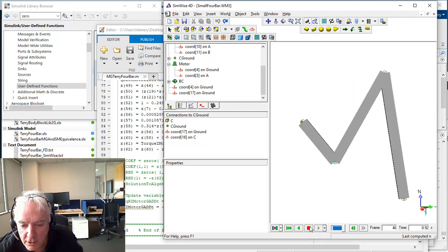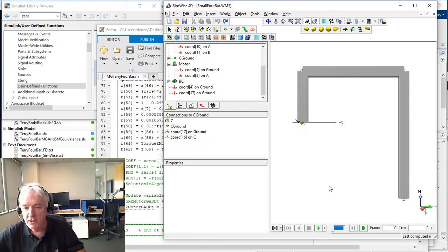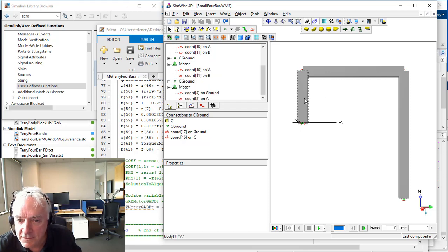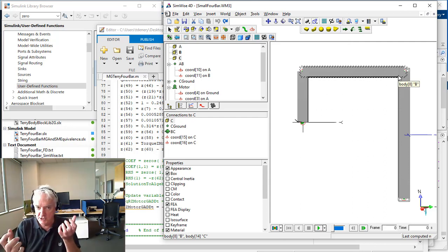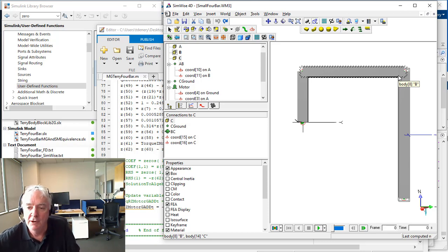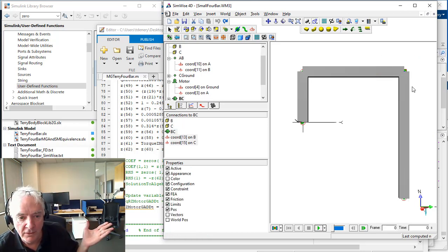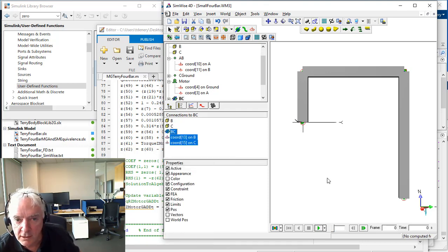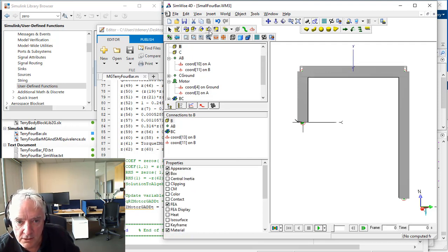If we look at our model as we have been working with it for the last couple of videos, it's a 4-bar linkage and everything. But what I want to get at is that this combination of bodies and joints has two expressions that ultimately represent two different types of mechanisms. The way I'm going to show that is, again, keep all my joints, keep all the lengths the same, but split this one right here so that I can get to the other configuration.